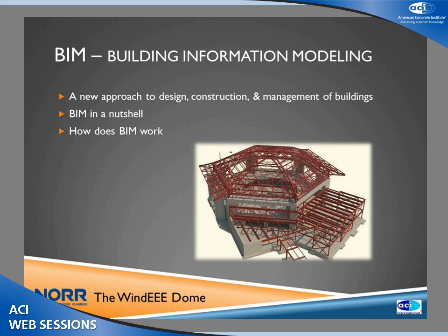Building information modeling is a new approach to design, construct, and manage buildings and infrastructure. In a nutshell, BIM can be described as the process of generating and managing building data during the life cycle of the building using 3D real-time dynamic modeling. A BIM model is essentially a virtual object database shared by AEC partners. It connects the 3D forms to non-graphic attributes such as material properties, schedules, costing, and performance information.